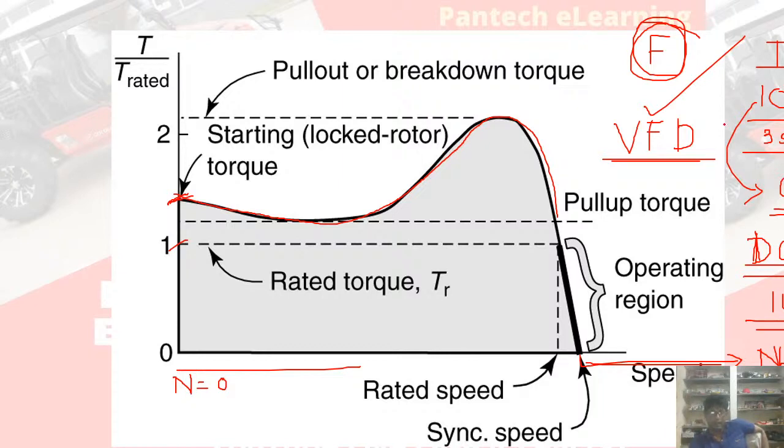Somehow I can reduce the current, but it should not happen that my motor is incapable of accelerating the load. It should be able to accelerate the load, as well as not take the inrush current for a long time. This is my requirement. To mitigate this requirement, variable frequency drives are introduced, which you will learn in detail in our successive lectures.